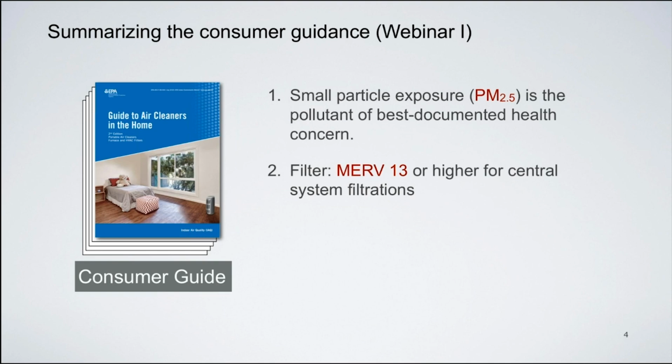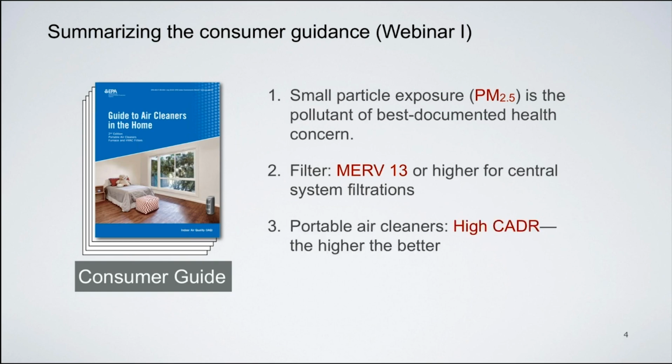But just what are we talking about when we say MERV 13? MERV is an acronym, like many acronyms, a little difficult to decode. MERV means minimum efficiency reporting value. That is a consensus standard developed by ASHRAE, the Heating and Air Conditioning Engineering Society. What it means is that the filter has a relatively high efficiency, especially a defined efficiency for small particles. That's the basic reason for the recommendation: you can rely on the idea that a filter of grade 13 or higher is going to take out a defined number of the small particles that we care most about.